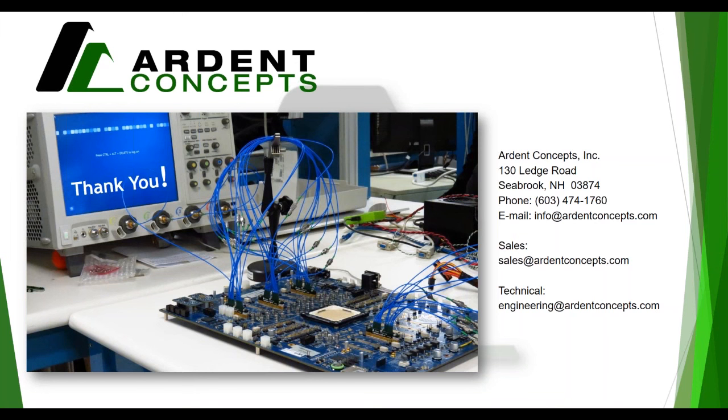Okay, and I guess kind of following along with that, what special footprint provisions or plating do I need? So we recommend hard gold, but we know that ENIG is very popular. And then also we have customers that use immersion silver for very high frequency applications where they want to eliminate nickel. So our general answer to customers is, as long as it's a noble metal, anything but solder can be used there.